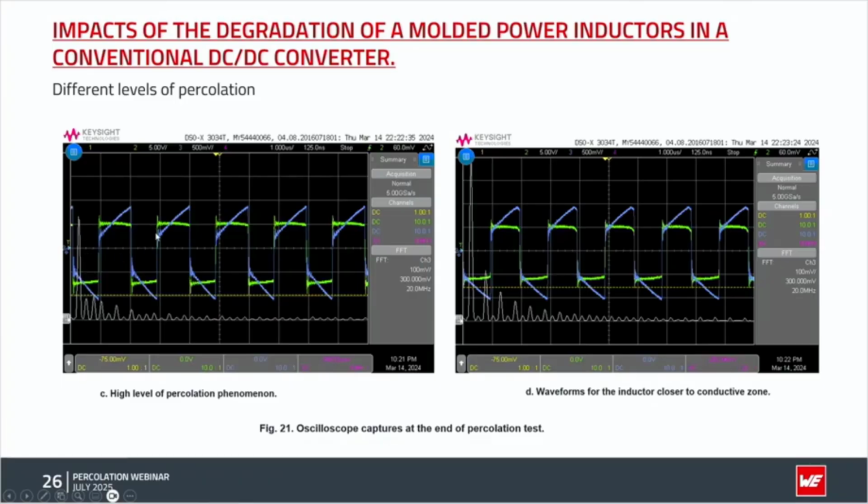So the one that is increasing is the step. And we have a huge amount of harmonics, and that is something we are concerned about. Why do we have this huge amount of harmonics? For sure, our model before represented a resistance. So it's a step, and a step in terms of Fourier series means an infinite amount of harmonics.